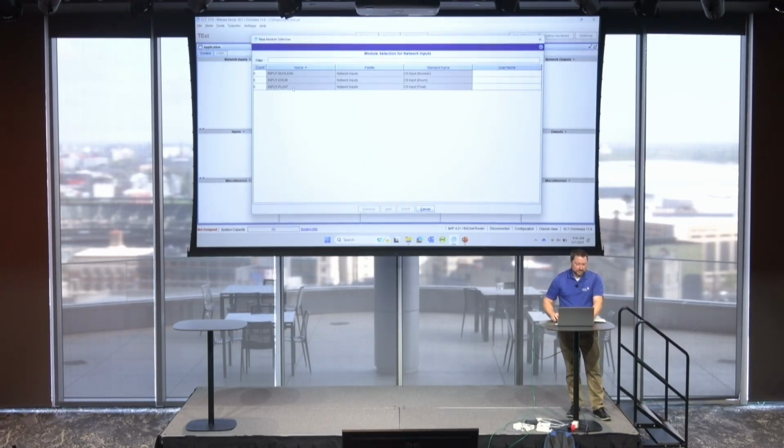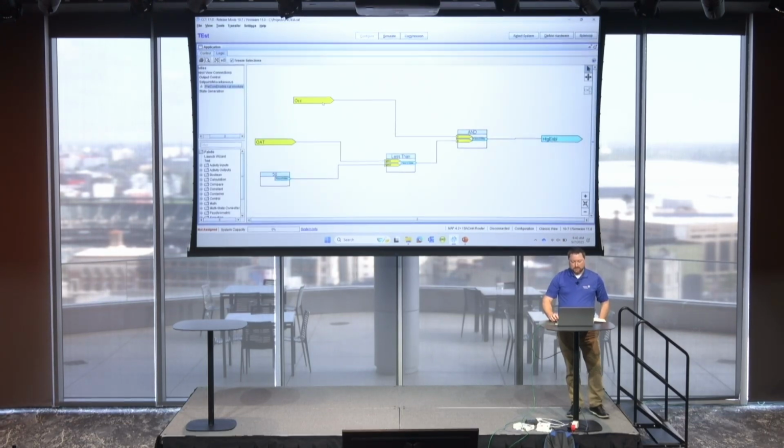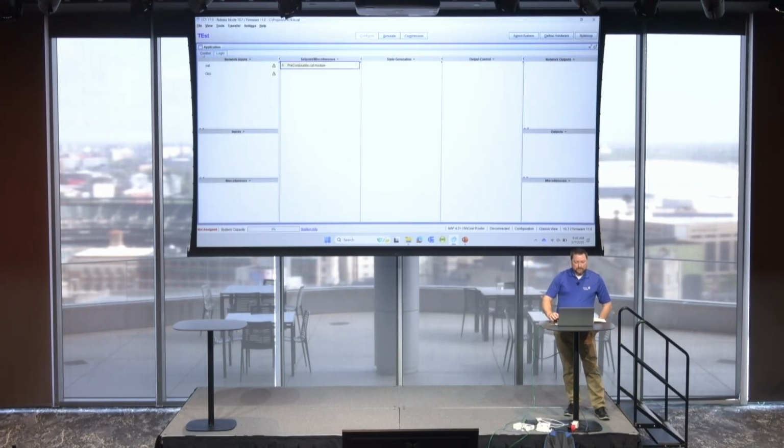And I'm going to build 2 points. This is just for show. We've got an occupancy point. We've got an outside air temp point. All right, so I've got this logic. It's, if outside air temp's less than 50 and occupancy is true, then enable some heat, right? So what I can do, if I'm enabling heat with a side loop, say I'm controlling discharge air temp,